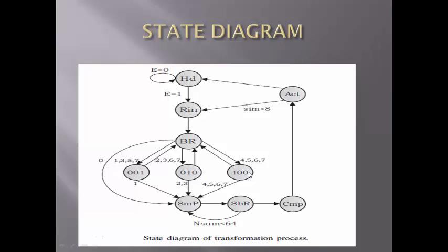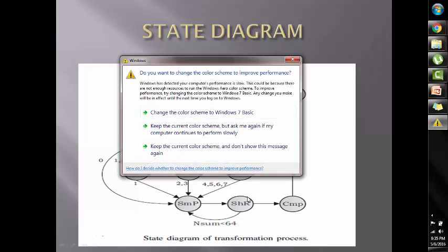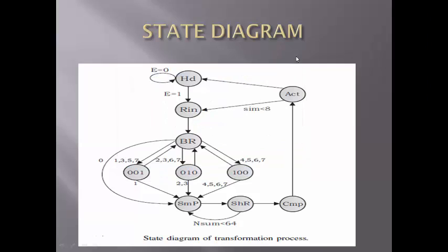The states S and T, SHR, take care of the calculation of the absolute value of the difference of each of the 64 pairs of pixels that form the transformed range block and the domain block. The calculation is performed by shifting the registers, accumulating, and the minimum distance is computed. In this case, the value of the accumulator is less than the value of the minimum distance.